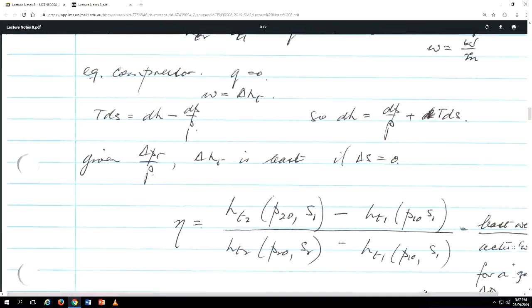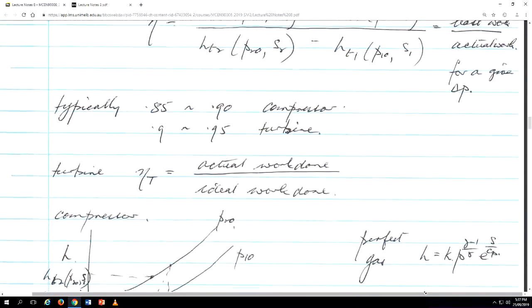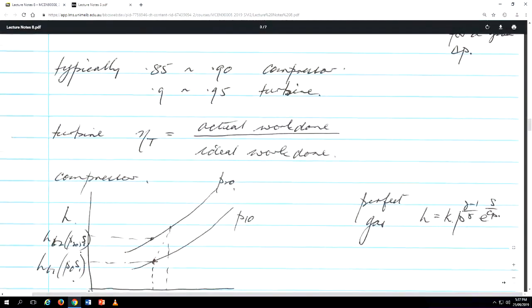Is that also related to the temperature? Because in turbine efficiency and compressor efficiency, in thermodynamics we use the temperature. Yes, indeed. These total conditions are, in fact, the total enthalpy. If it were a gas, you know what the total enthalpy is in terms of temperature. So it's a statement of the temperature. Yes, exactly. You're essentially finding the enthalpy by measuring the total temperature.